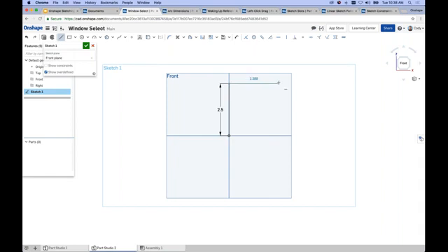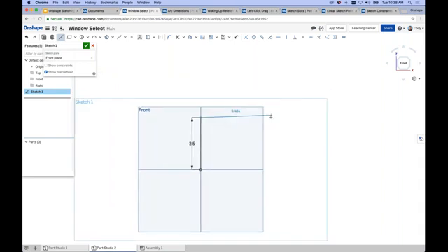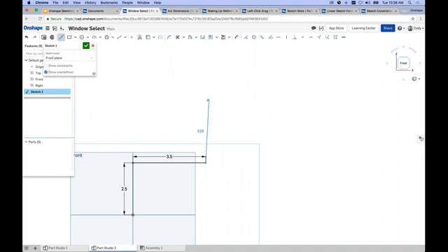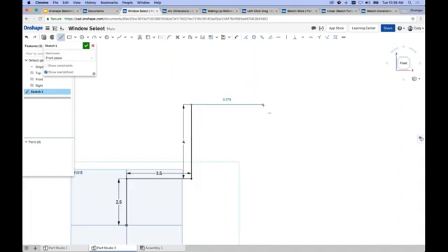And we can keep going. So now I'm still in the line command. I can keep going. Let's say that I want another line. Left click, same thing. You'll see that box appear over the dimension, 3.5, enter, and now I've added a line at 3.5. So again, it's a very quick way to sketch geometry and define geometry at the exact same time, right?